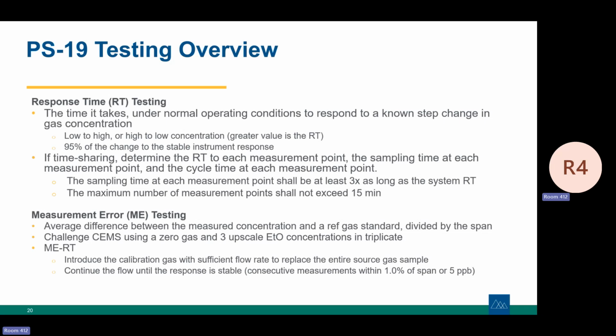Similarly, measurement error testing, the difference between the measured concentration of a reference gas and your measured gas. Challenge it using 3 different upscale levels, so low, medium, high. Run that in triplicate, calculate your measurement error and response time. Pretty straightforward.